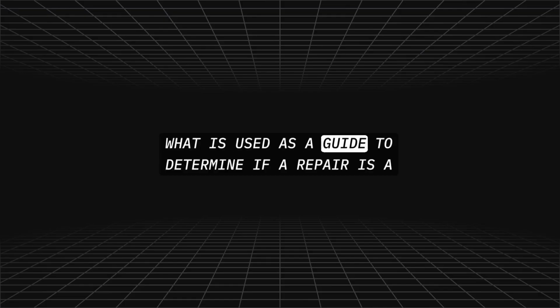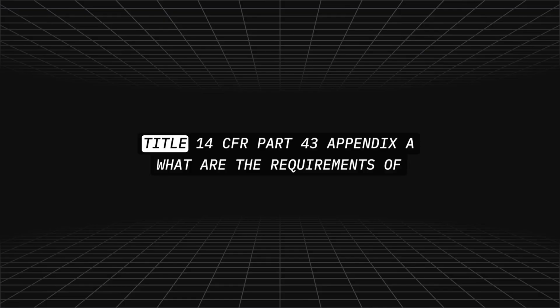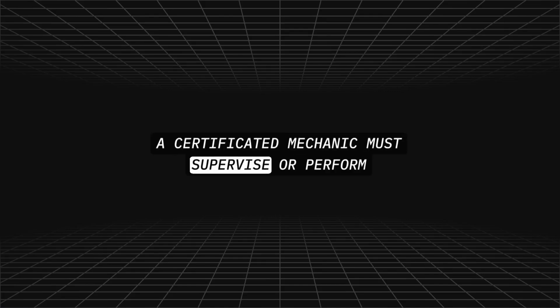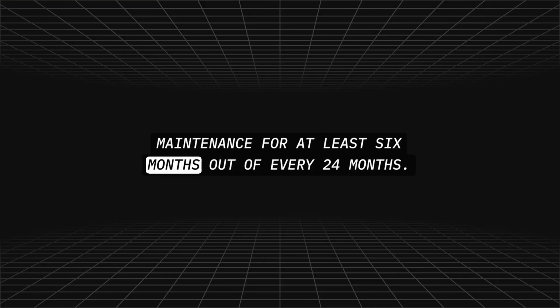What is used as a guide to determine if a repair is a major or minor repair? Title 14 CFR Part 43 Appendix A. What are the requirements of recent experience for a mechanic? A certificated mechanic must supervise or perform maintenance for at least 6 months out of every 24 months.